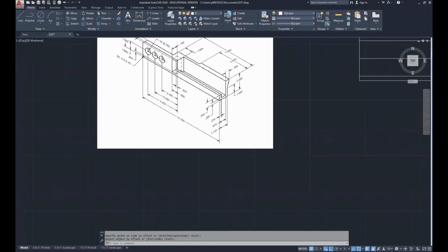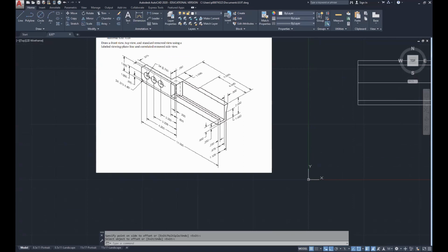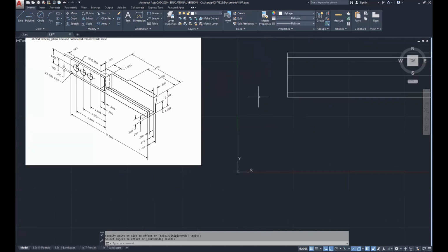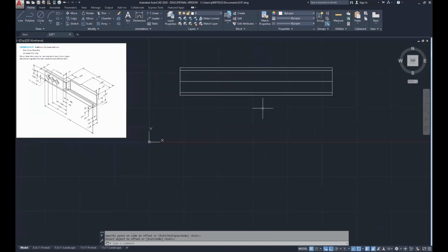Now, take note also, if you look at the position of the dimensions, they tell you what face they are on. These are all on the front face that are slanting to the left. And then all these slanting to the right are the right-hand side dimensions. Make sure to keep that in mind when you're reviewing the drawing. Let's go ahead and get some of these dimensions from left to right taken care of.